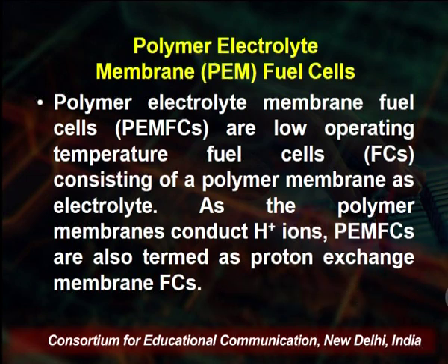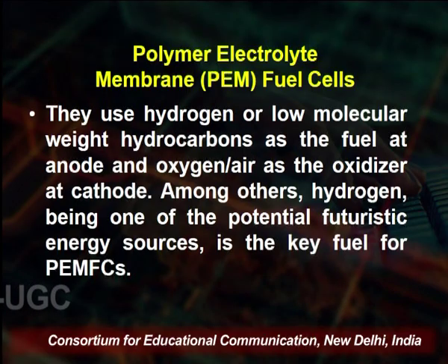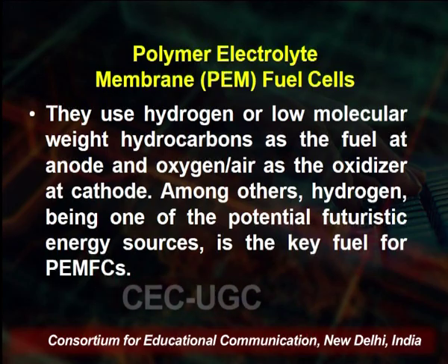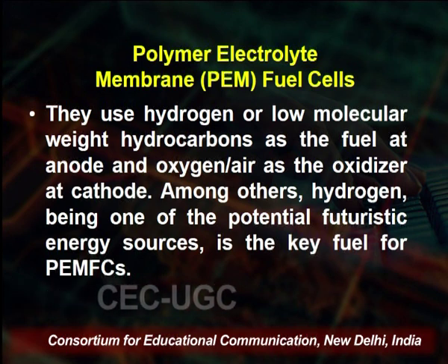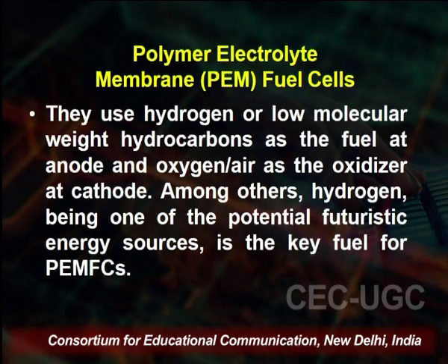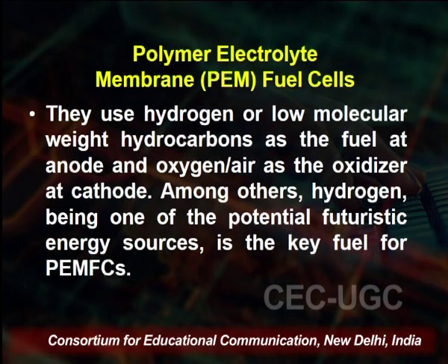As the polymer membrane conducts hydrogen positive ions, PEMFCs are also termed proton exchange membrane fuel cells. So it is also a proton exchange membrane cell. They use hydrogen or low molecular weight hydrocarbons as a fuel at the anode side and oxygen as the oxidizer at the cathode side.